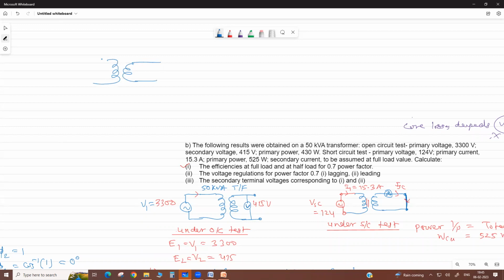If we test physically, we need a load. But in your factory, when we test the transformer, we require a load bank this big. Then from where do we arrange the load? Suppose we arrange the load, then there is unnecessary power loss in this load. We waste energy in testing the transformer. That's why there is an indirect method of testing.